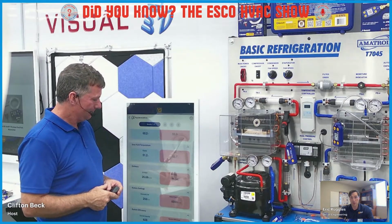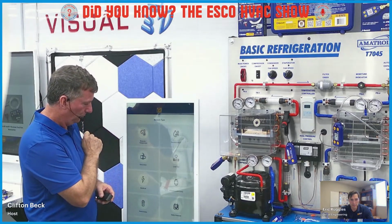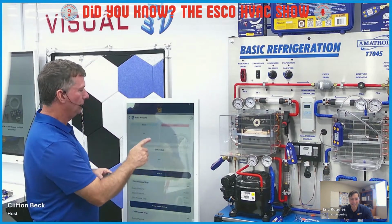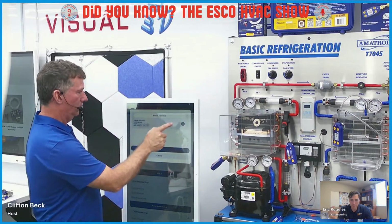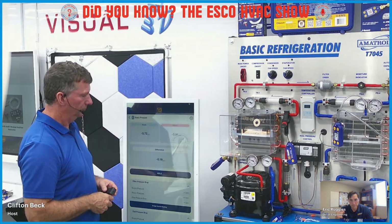Then the last one is what you have hooked up, which would be the manometer. So if you go back out to the sessions, bottom right is static pressure. You're on the right. And then you just have to find the one sensor. It'll show you both red and blue. Got it. And then it'll show you active pressures and the differential. Okay.